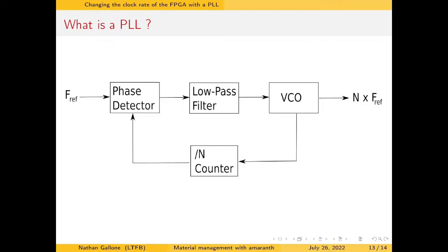So let's implement this. But before we dive in, note that I'm about to program on a Lattice ICE40 UP5K board. And because we are talking about material, the Amaranth instantiation may vary from one board to the other. In fact, it's very likely to be the case. Some boards require to use buffers before and after the PLL to use its signal. Some will need to use different PLLs following where the signals you wish to use are coming from. You see, it still depends on the board you're using, despite the fact Amaranth tries to unify the practices of FPGA.